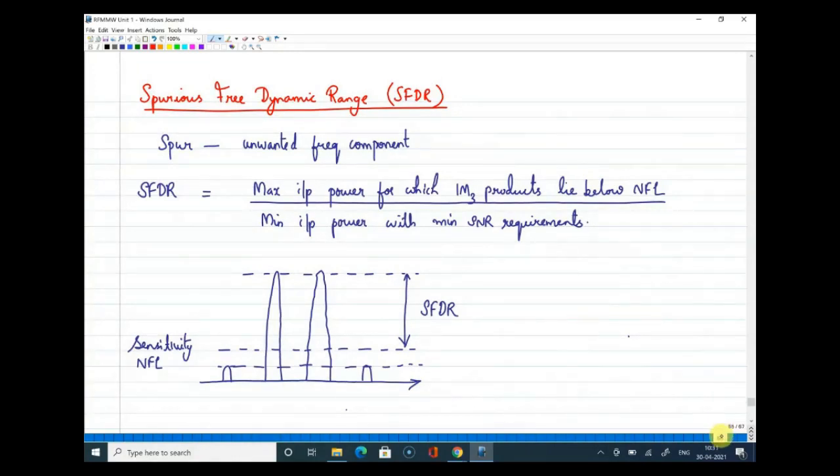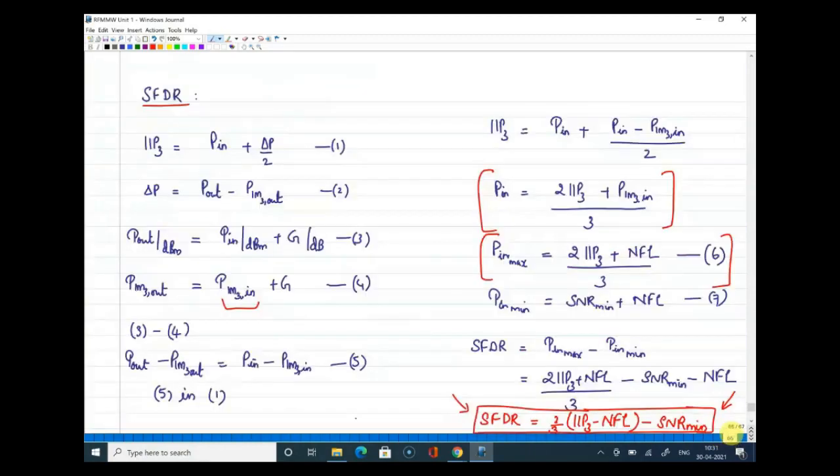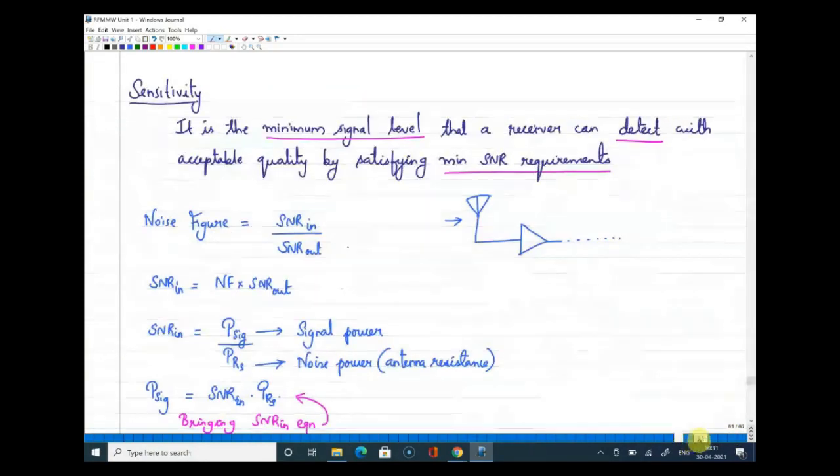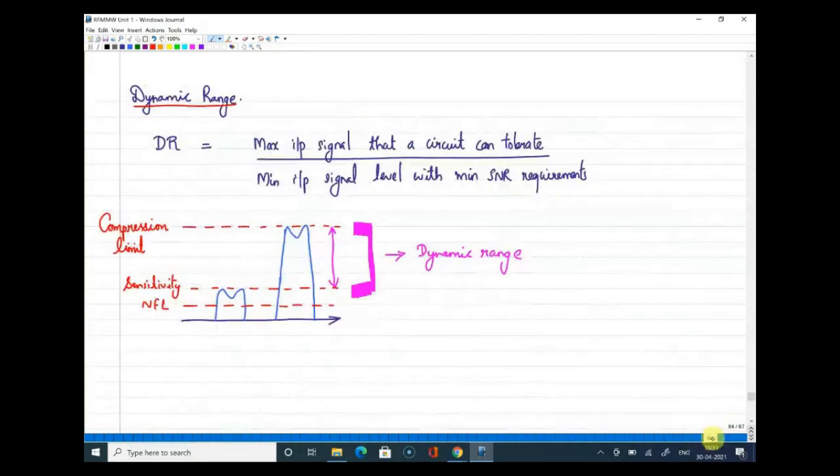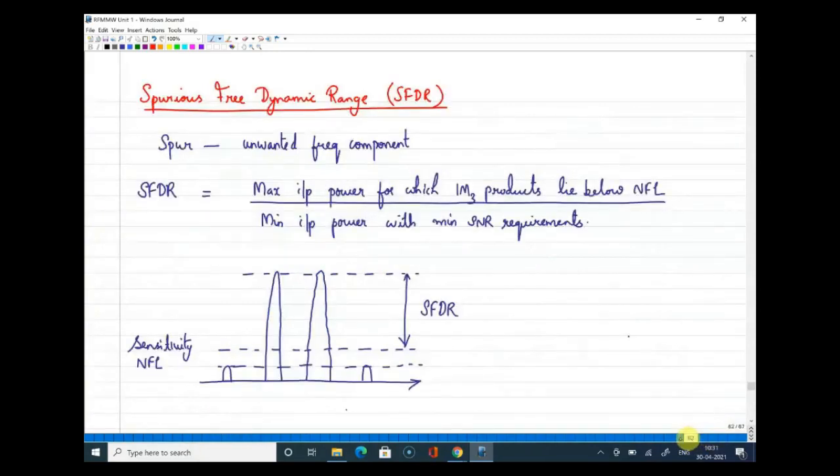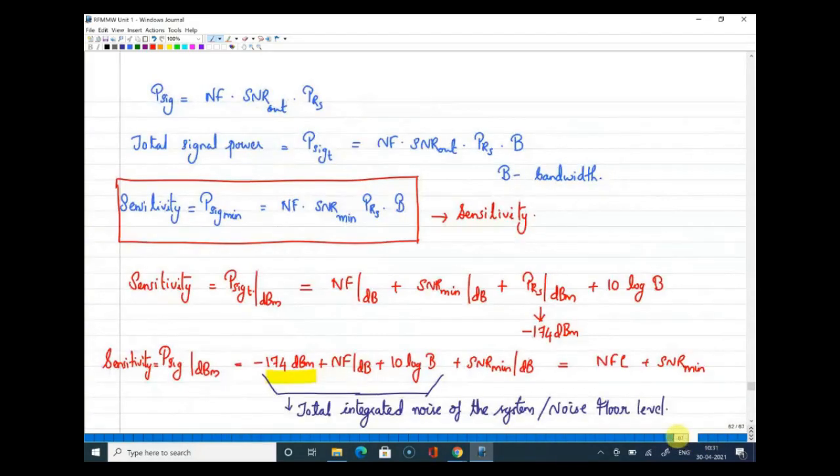If you look at the terms under noise floor level, the bandwidth remains the same, and the receiver minus 174 dBm remains the same. But noise figure is the single term, so let me check and get back, because there can be a small difference in the noise figure.